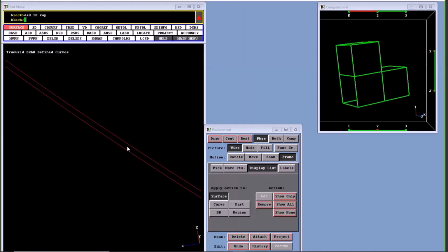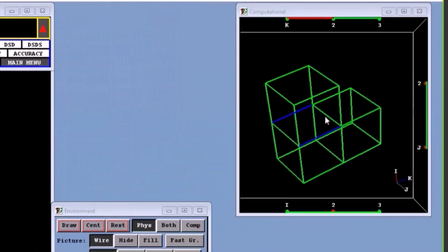It's the routine algorithm. It's great. It's a really elegant algorithm. So even when you want to intersect two surfaces that don't quite intersect, TrueGrid does a wonderful job of it. So you don't have to fix up your geometry. Your tolerances, your errors, should be relatively small compared to your element size.